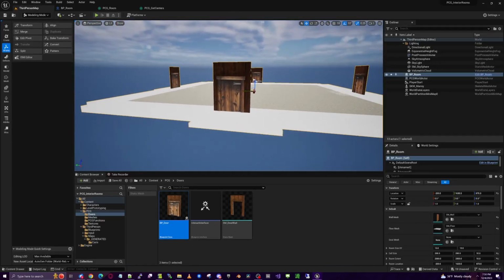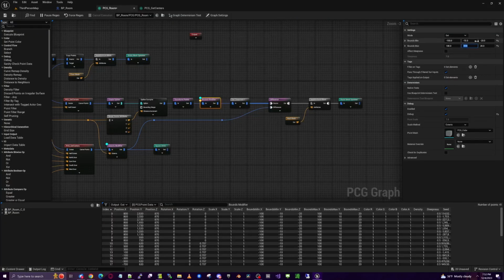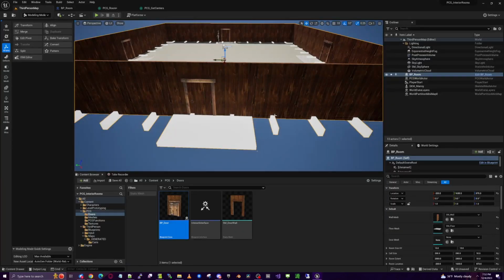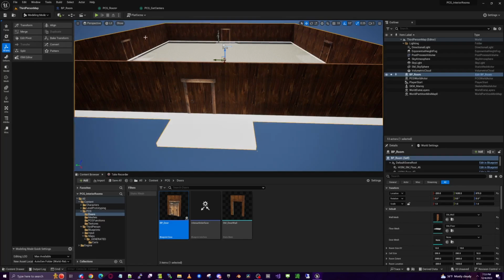Okay, yes, now we are seeing those points. They're too big. So I change this bounds to -100, -10, -20, 100, 10, 20. We can look at the size of this. Now it's super skinny. What we want is for this extent to cover the wall of the door correctly and these extents to cover the walls correctly. They are currently wide this way and skinny this way, so we need to flip that. So we need this to be -10 here, -100 here, 10 here, 100. This should give us the size of our wall approximately that way.